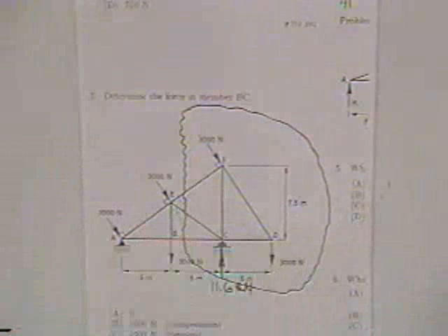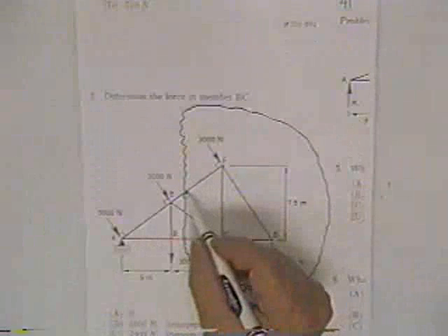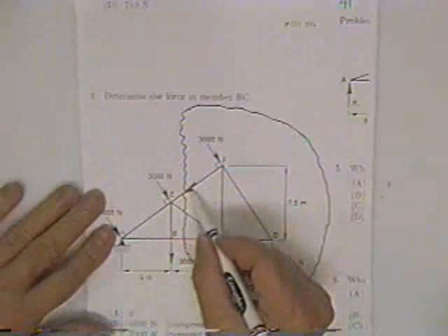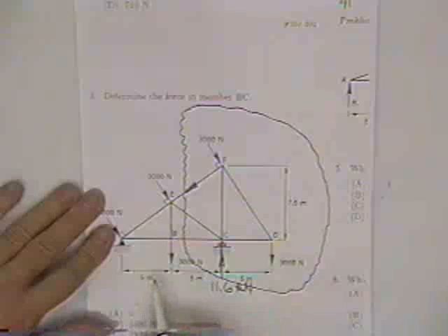If you remember a minute ago, I guessed that the arrowhead for EF was a tension pulling on the joint. The only way something can pull on the joint is if it's in tension. A tension arrowhead. Now I don't know if I would have found out that was true or not, but if you do, you must show that arrowhead as a pulling arrowhead on the other end too.